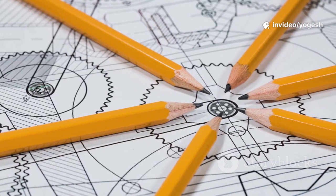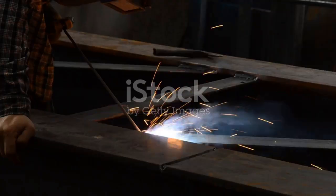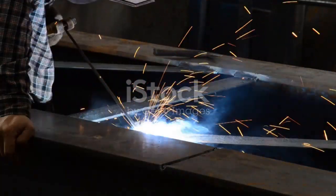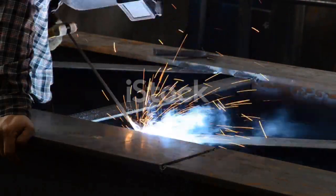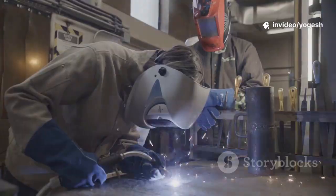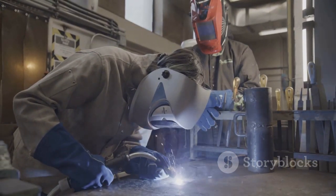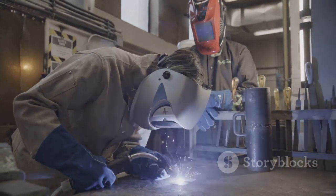Advanced symbols allow engineers to specify complex welds and sequences. Multiple reference lines indicate multi-step operations. Each line represents a separate weld, shown in order of execution. For example, a groove weld on the first line, followed by a back weld on the second, clarifies the sequence.